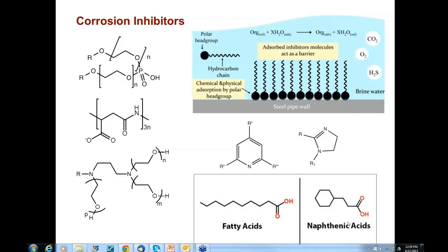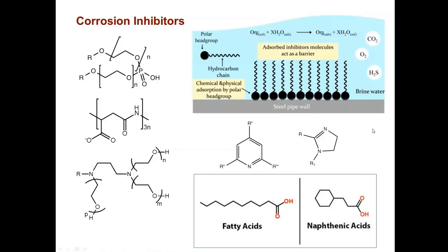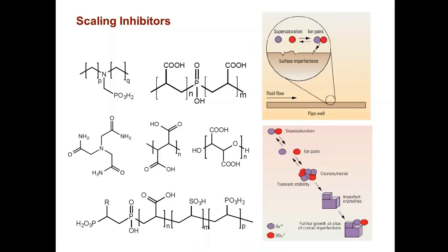This can be as simple as fatty acids or lactic acids or different types of chelating and electron shuttle modifications as inhibitors of part of the coating or the component itself of the fluid. Scaling inhibitors are basically inhibitors, ligands, polyelectrolytes, polymers that can control aggregation, preventing the deposition from supersaturated high-brine fluids or preventing their formation as aggregates or clusters in the first place.